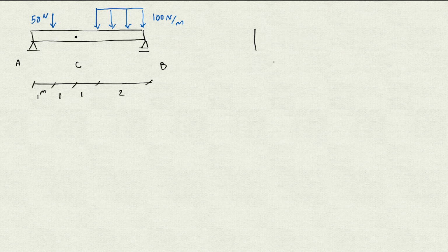The other point I want to make is that when we are working with this, do not change the force until after you split the section and isolate the section you want to work with. So do not replace these forces for your section view, for your section analysis. Try to keep it the way it is, and after you cross-section it, after that you replace the forces with the resultant one.